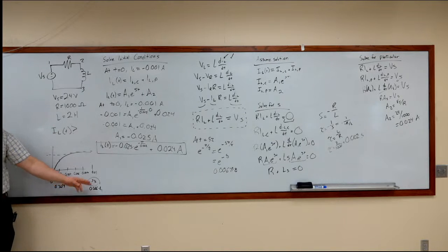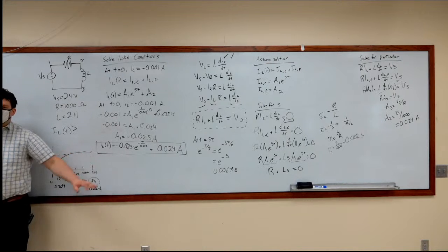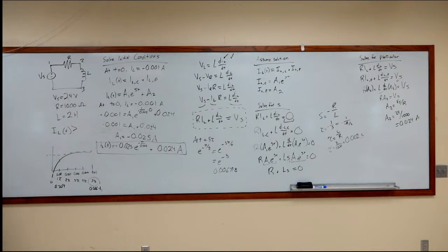At this point right here, this is within 0.02 volts. So Vs may actually drop or increase. At this point, you're now in the noise level of the actual power supply, which is why we say 5 tau is close enough.